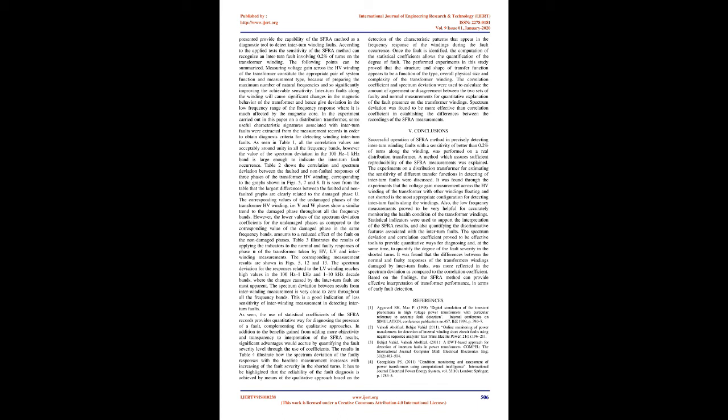The comparison of HV and LV winding measurements in Figs 5 and 12 indicates that contrary to HV winding measurements, in which the effects of interturn fault reach into the midrange of the frequency response up to 100 kHz, in LV winding measurements, high frequencies above 40 kHz are not affected by the fault.